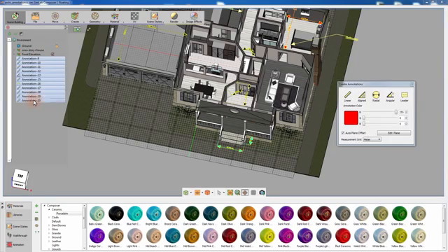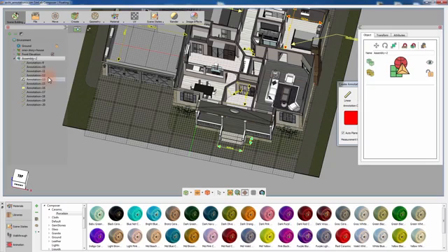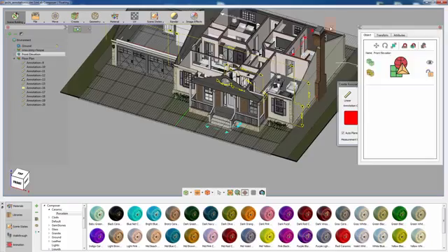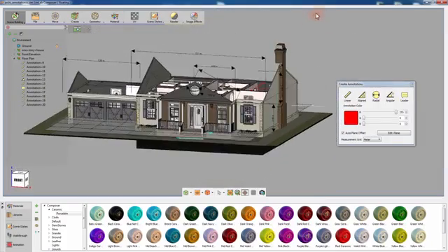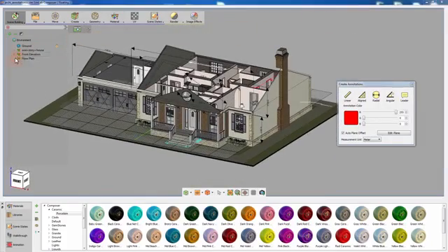Select the recently created annotations from the object tree to the left, and right-click and select Add Parent. Set the name to Floor Plan. Now that all the annotations in the scene are grouped according to their corresponding view, you can hide and show them as needed.